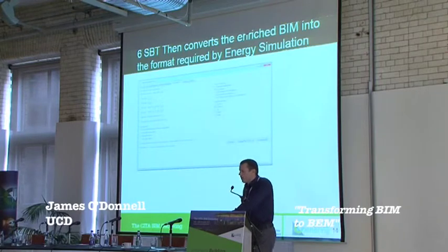The space boundary tool itself is a semi-automated process, so there are some rudimentary inputs that are required, for example, number of time steps per hour. I don't know how clear it is here. You can select the terrain for your building. You can talk about the different types of shading and shading algorithms you'd like to use within the package. They all have a different effect on the accuracy and the runtime of the particular model.